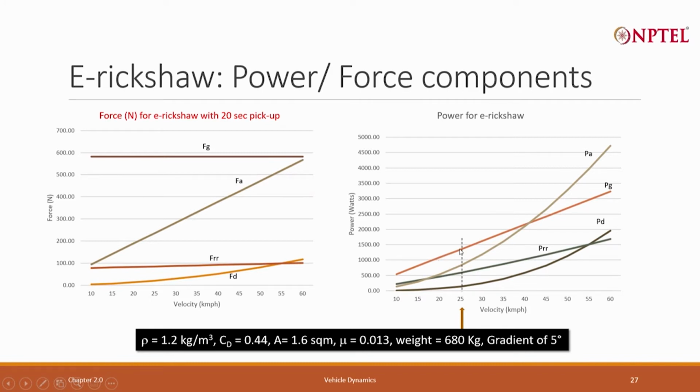1.5 kilowatt. If I really travel at 15 kilometer per hour, because the curve here is done at 3 times the velocity, you will actually have to see the 45 kilometer barrier. This is 1.5 kilowatt, including rolling resistance and drag.